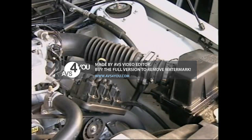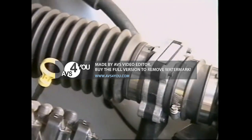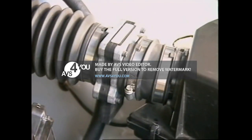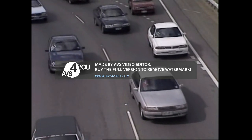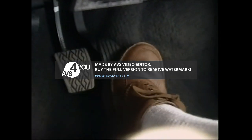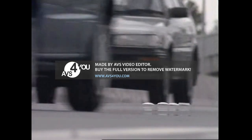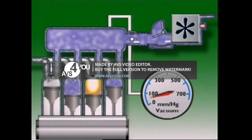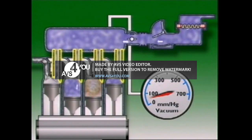The amount of air entering the engine must be measured, so that the amount of fuel injected into it forms a mixture to suit the engine operating conditions at that time. The volume of air entering the engine varies according to the position of the accelerator pedal and the engine speed and load. Changes in volume are reflected in changes in manifold pressure between the throttle plate and the intake ports.